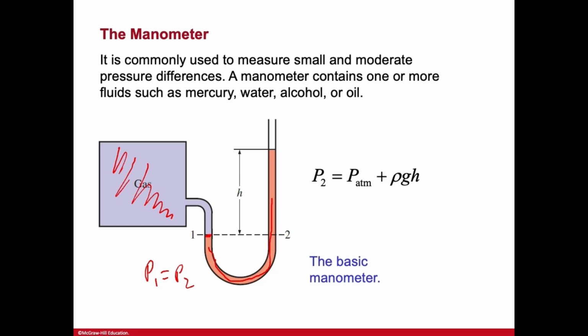Now for this liquid column, we go about a similar force balance as what we did before. Unlike the last slide, where we used a barometer, on the top side it is open to the air. So what will the pressure be here?